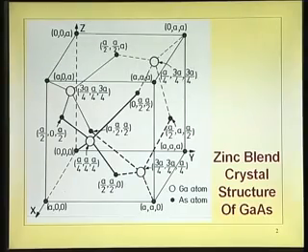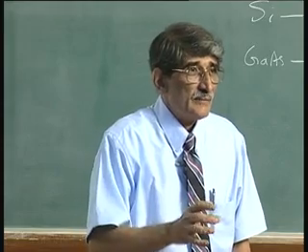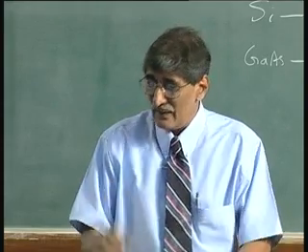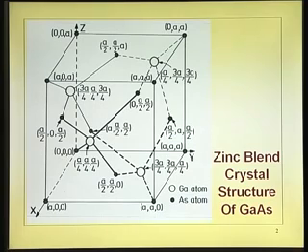So, on an average, since there are 4 valence electrons, this gallium atom forms covalent bonds with its 4 neighbors, and who are these 4 neighbors? They are arsenic. And if you take arsenic atoms, who are the neighbors? Gallium. Okay. So, this gallium atom, which are the neighbors? One at the corner here, okay, and other, you can see the solid line is drawn, and the other one is here. We will go to this room and see, the structure will become clearer. That is this phase.